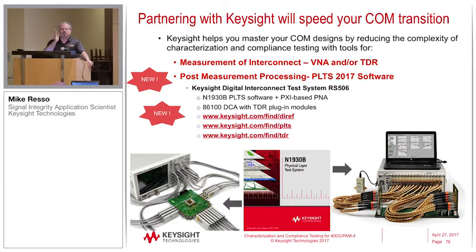Each one of those PIXI modules that's standardized is a 2-port VNA. And you can basically pick whatever frequency range you want for your VNA measurements: 3 gig, 6 gig, 9 gig, up to 26.5 gigahertz today. And you can go from 2 ports up to 32. So this will handle the 12-port VNA measurement that you need for COM. And then the DCA that Jeff has back there has TDR plug-in modules that you can have up to 16 channels. Right, Jeff? Yes, sir.